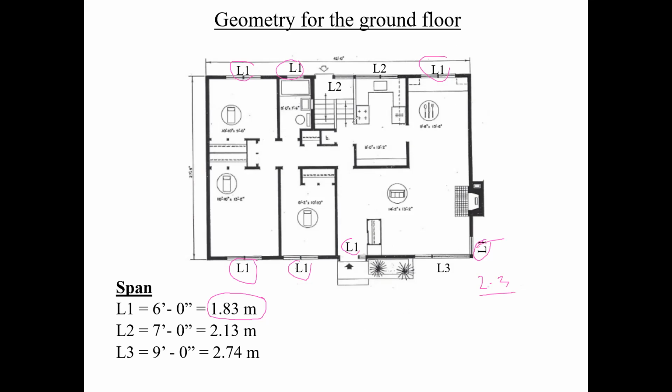Now, the biggest one, the one that we did right now in the lecture, would be this situation here. Now, this is not a column here, guys. That's a mullion for a window. And this is not a column. That's just a door frame. So when you look at it from this point of view, this is exactly the same view that we had in our assignments. If I look at that view, I have a big window here, I have a column, and then I have an opening for a door, and that's what you see in between here. I'll do a different color. This here is the door frame, and this is the mullion of the window. So that's not another column.